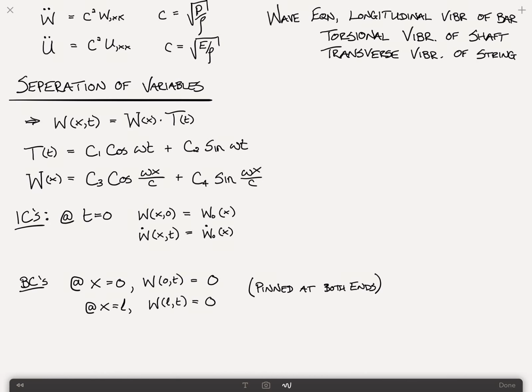And we have another example of how we solve for omega. Omega is fundamentally the eigenvalues, and we find it by plugging in the boundary conditions, and we get some sort of an equation that can get solved for omega. This is omega, this is W. I don't mean to confuse you with those two. Okay? So omega, which is the frequency of vibration, there are an infinite number of frequencies of vibration because it's an infinite degree of freedom problem. It's a continuous system. And those are known as the eigenvalues, and the mode shapes are known as the eigenfunctions, as opposed to eigenvectors that we see in discrete systems. That's all I'm going to say about this now.